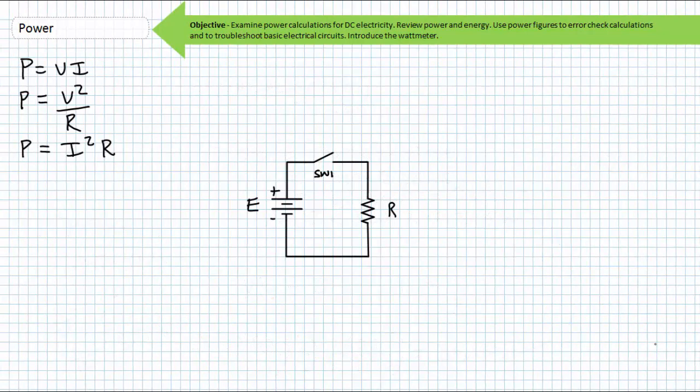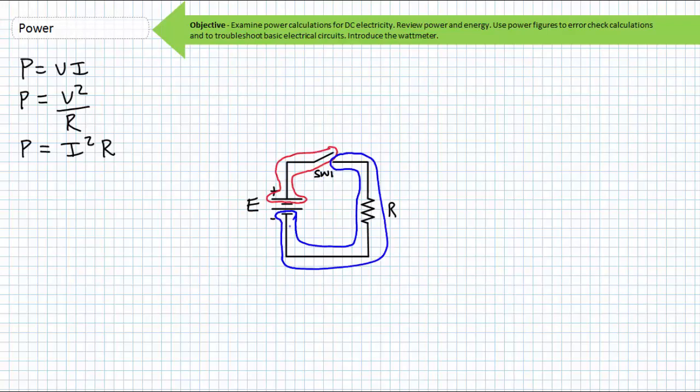Consider the two extremes of voltage and current in associated power calculations. Consider a switch in series with a resistive load element. The resistance of an open switch is infinite and no current can flow through it. That being said, there is a voltage drop across it, in this case the full voltage supplied by our source. However, with zero current flowing through it, what is the power loss associated with this switch? Regardless of the magnitude of the supply, with zero current flowing through the switch, the power loss for an open switch is 0 watts, because there is a voltage drop across it, but no current through it. Charges need to move to carry energy to a destination.